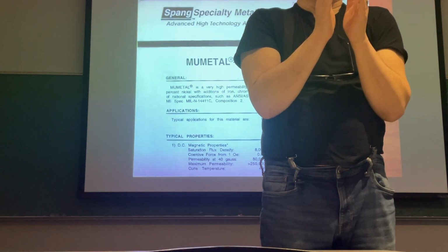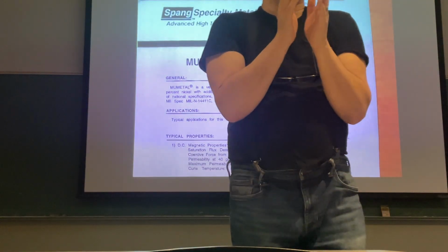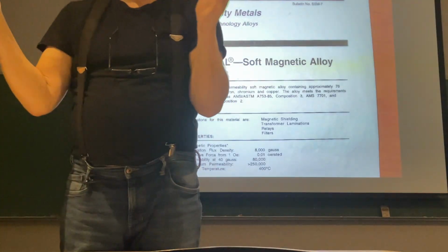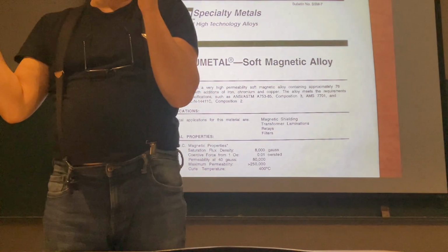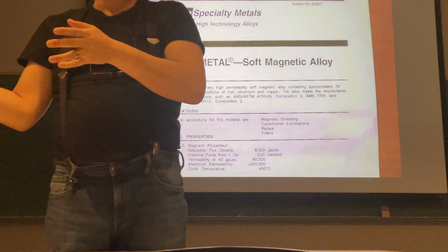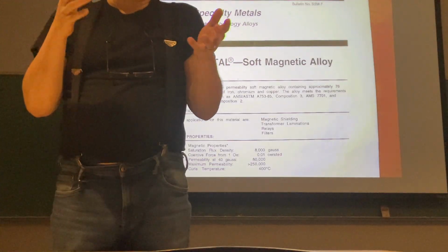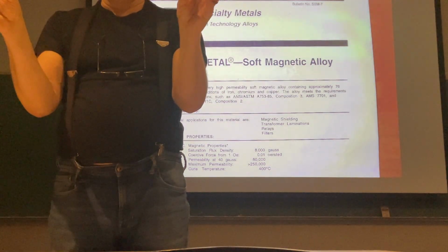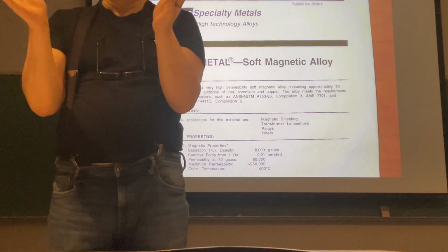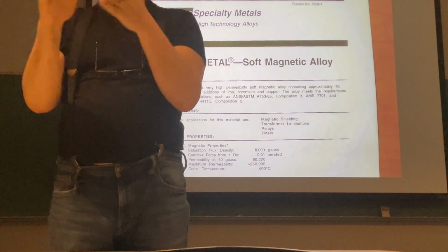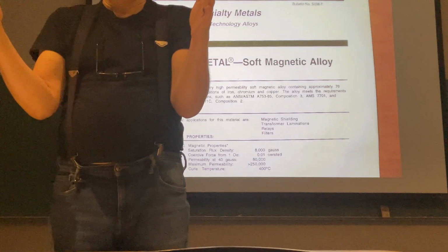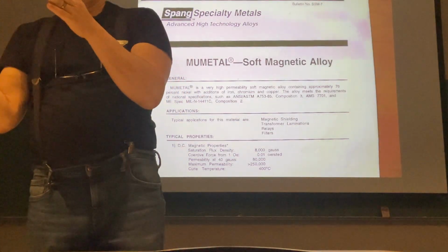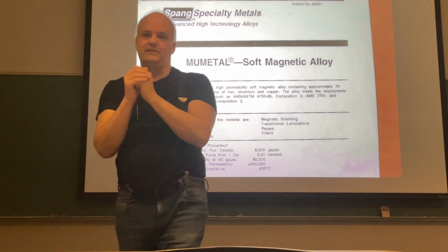It gets smaller. And you can make it, the problem is when they make it, they have to make it in one batch, and that batch is pretty much all the same. So you have to use it for whatever application for that kind of thermal expansion coefficient. Whereas you make another one, it could be a little different. It's hard to make perfectly. Because if you have two materials that expand differently, they could give an overall difference of what you don't want. So if you're going to use it for a cavity or something like that, that doesn't change shape at all when it heats up or cools down, you want to make sure you make it in the same material. So it's an interesting technical problem.